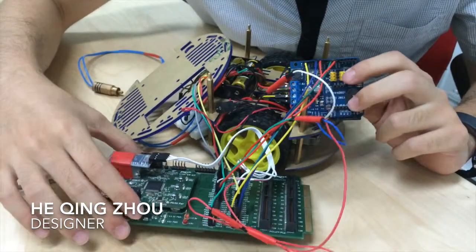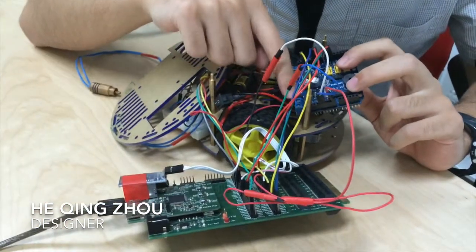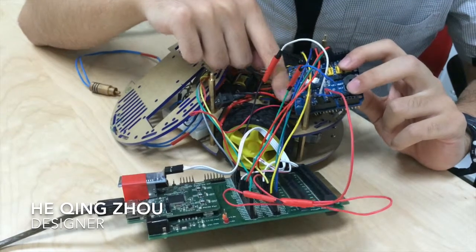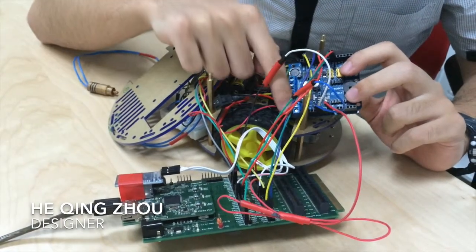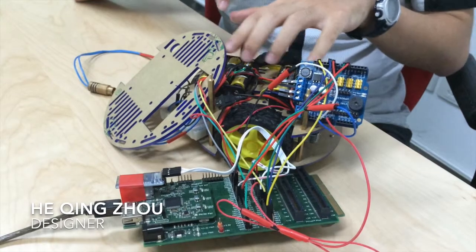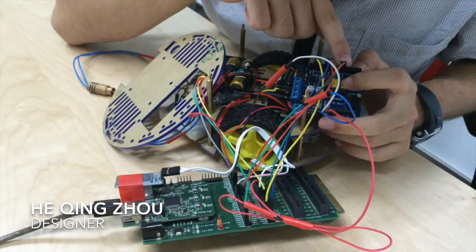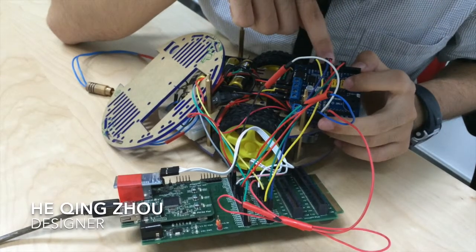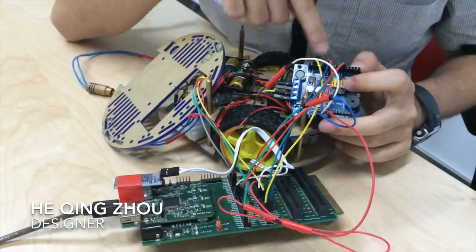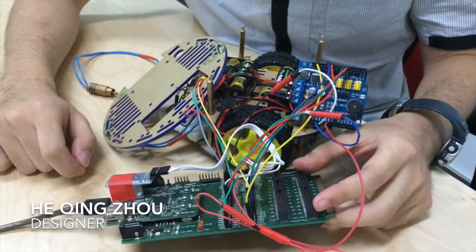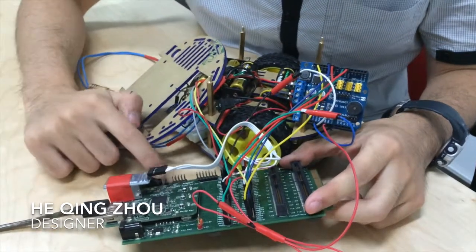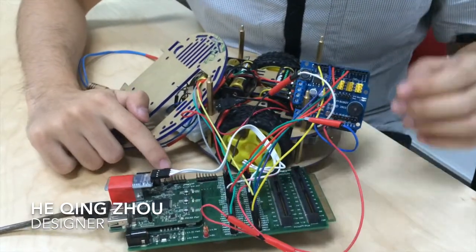And then in the driver board we have first two pins, V-in pin and the ground pin. These two pins directly connected to this 6 batteries power source. And then we also have here 2 A-in port and 2 B-in port. These 4 ports will directly receive the input signals from PIC's I/O port.